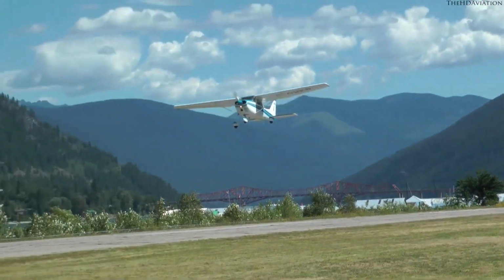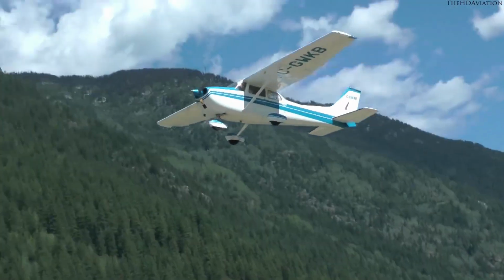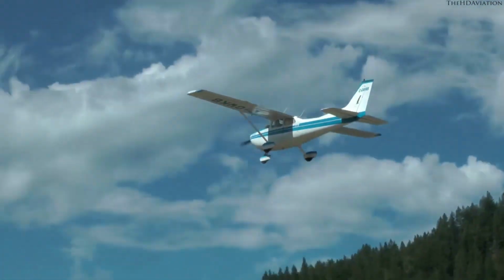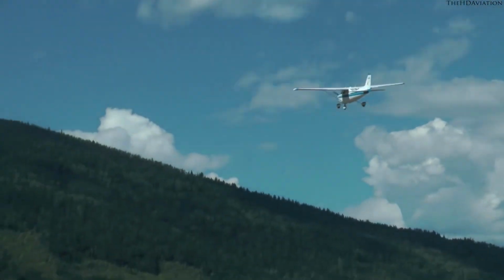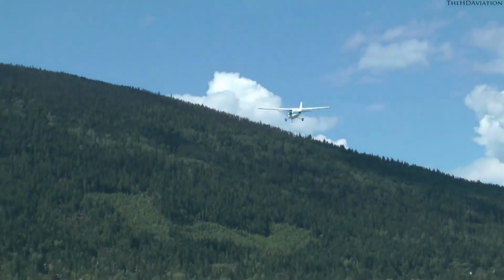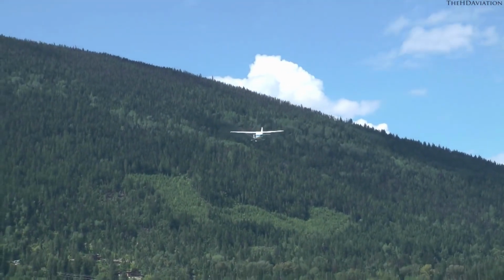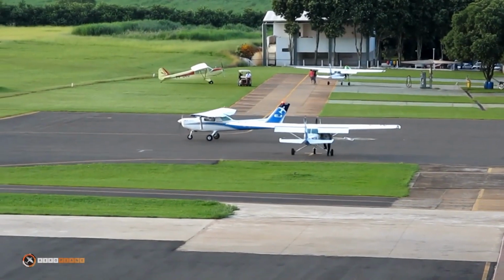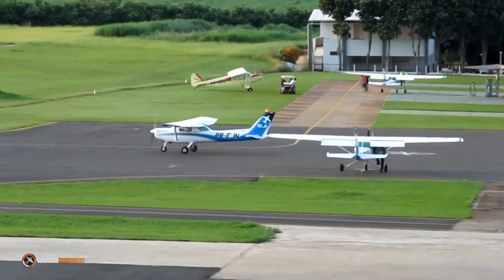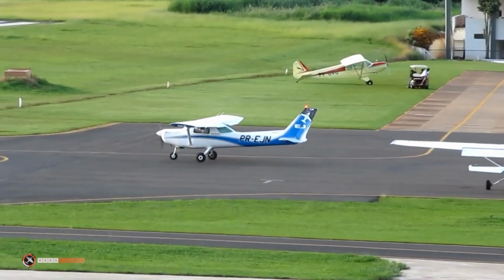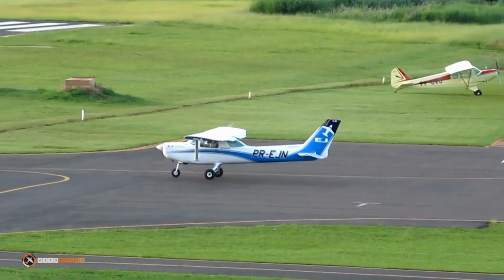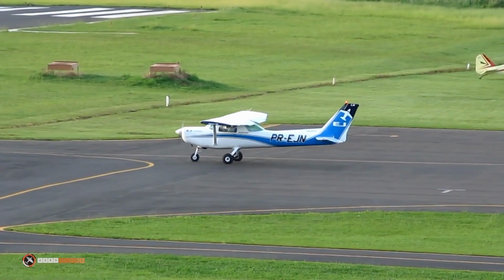The chosen cruising speed of 50 meters per second, the takeoff speed of 30 meters per second, as well as a cruising altitude of 10,000 feet were inspired by the Cessna 172 and similarly sized UAVs. The Cessna 172 has an approximate total weight of 757 kilograms, and our decided upon weight of the total aircraft was 1,000 kilograms.